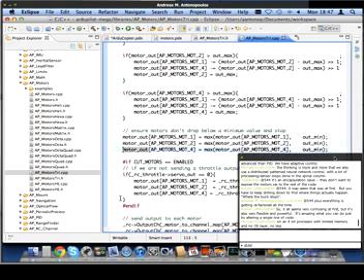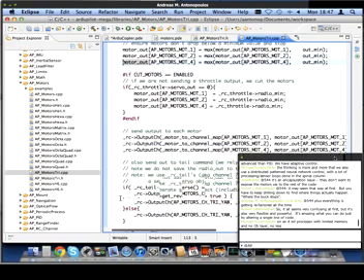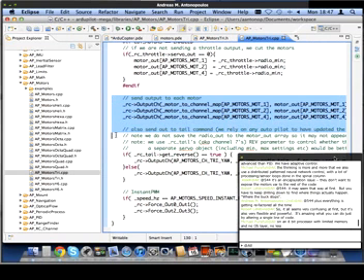Then we also make sure that the motors don't go too low, i.e. we don't want them to stop spinning completely, so we make sure they don't go below a certain value, which is I think about 130 or so. There's a little bit of cutoff stuff which I won't worry about, but basically it's just cutting off the engines if they need to be cut off.